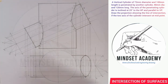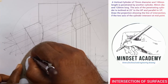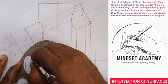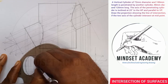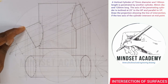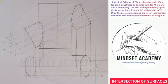Now what you need to understand, if you're looking at it from here, you will not see this side here. So you only see one part of it, which is this part here. The rest will be hidden line. The reason is this: if you're looking at it from here, you cannot see this because this will block this up, right? This is what we're actually having.